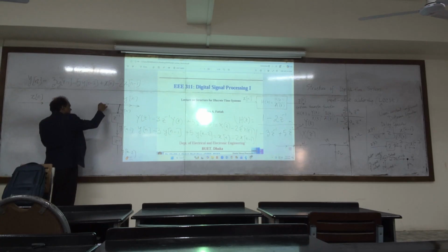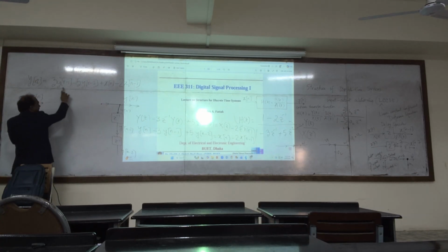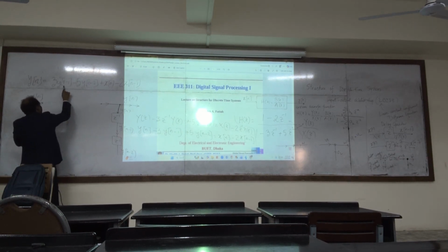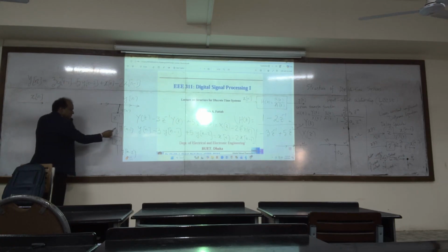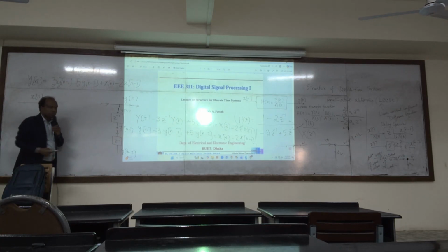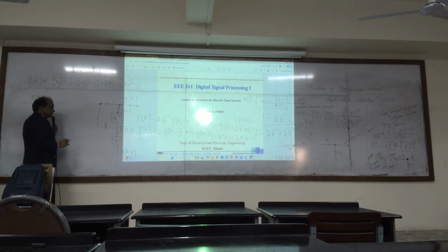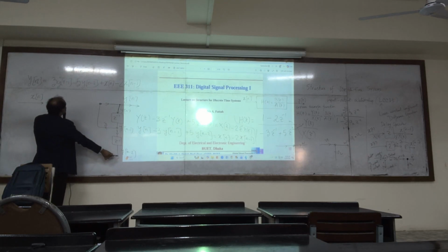This is the adder. What do you have to add? You have to add x(n). X will come here. You have to get 3y(n-1), so this is y(n-1). You have to bring it from here to there and multiply by 3. Then y(n-2) is ready. You have to bring it, multiplied by minus 5, and then bring it here.